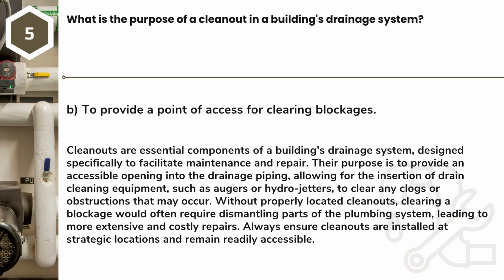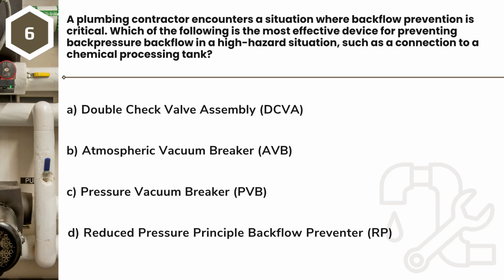Always ensure cleanouts are installed at strategic locations and remain readily accessible. Question 6. A plumbing contractor encounters a situation where backflow prevention is critical. Which of the following is the most effective device for preventing backpressure backflow in a high-hazard situation, such as a connection to a chemical processing tank?